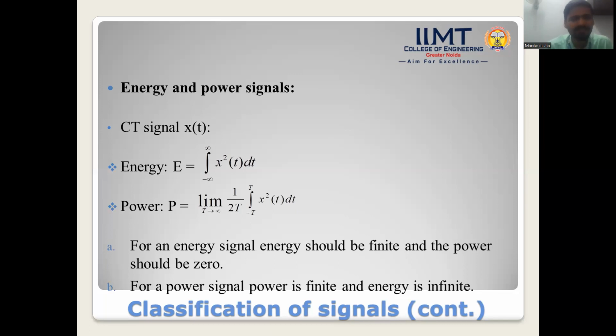So one thing we have to remember: for any energy signal, the signal energy will be finite. If a signal is an energy signal, then energy will be finite and power will be 0. If the signal is a power signal, then power will be finite and energy will be infinity. So these 2 points A and B you have to remember for the energy and power signals.